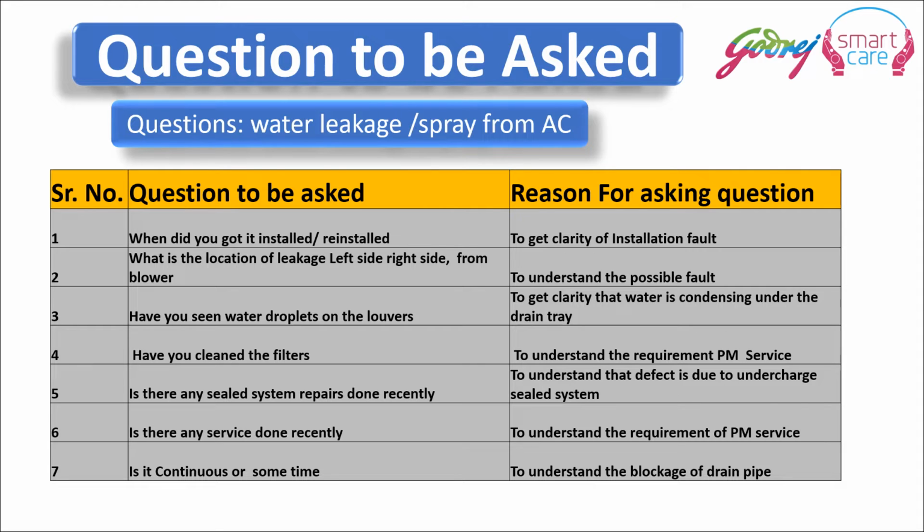If there are any sealed system repairs done recently and the repair has not been done to full satisfaction, then there is a chance that there may be less gas or excess gas in the system, which may lead to sometimes excess cooling or ice formation, or maybe less cooling. These defects can also cause water leakage.